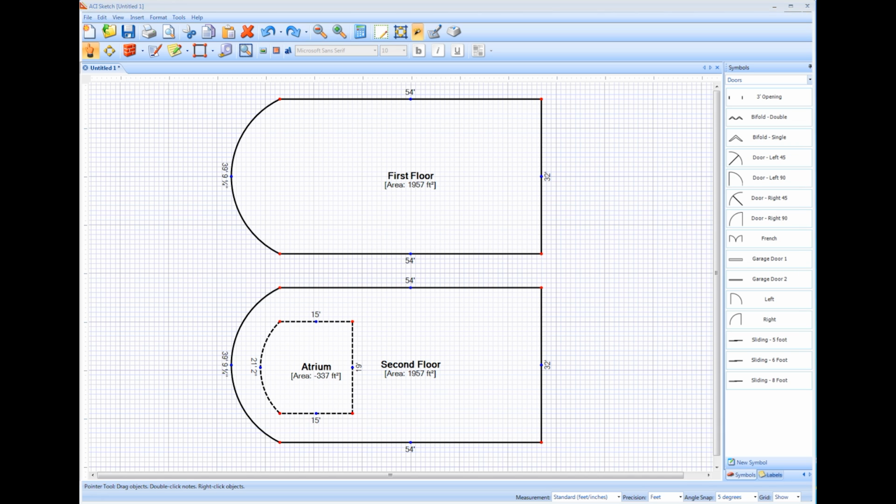Another powerful tool in the ACI Sketch repertoire is our area bisection tool, or the ability to carve off an area and create a new property. I had mentioned previously that in our Draw First application, you can trace the entire gross building area of a floor plan. Now, if this upper right corner was actually an attached garage, I don't have to retrace a new garage area over top of it. I can click into my wall tool and simply left click and draw out that attached garage. You'll see that I drew two walls, and now I've got another subsection of that first floor, that GLA.